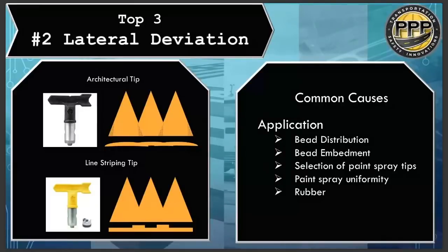I wanted to bring up we had a question about flow rates of your paint machines and so forth. And since the questions are being asked, I might as well address that a little bit here. The question was more specific to how do we check for the flow rates, and does a third party do that? And I know, Mike, in your symposium, you actually go over flow rates of beads and paint. And some machines actually have that. They'll tell you what mil thickness you're putting down, and it basically calculates the gallons you're going through and the feet you're measuring. And that's really the best way.